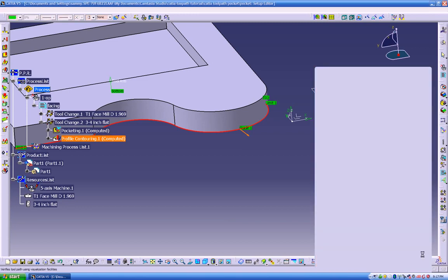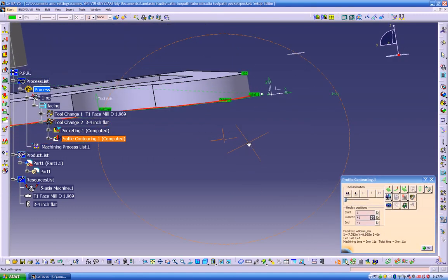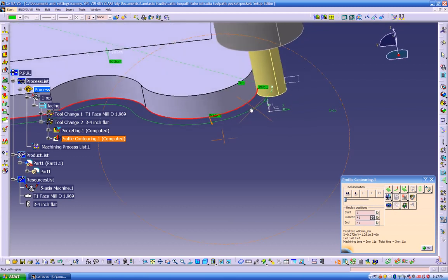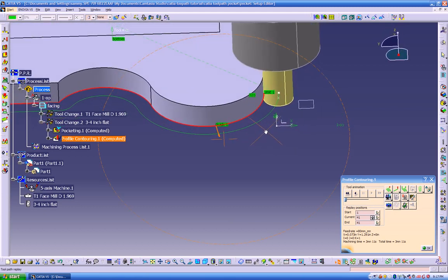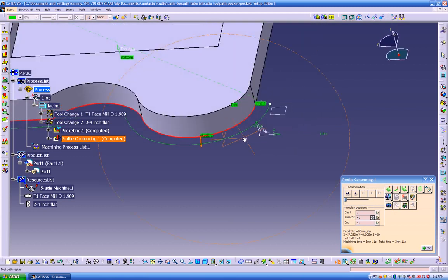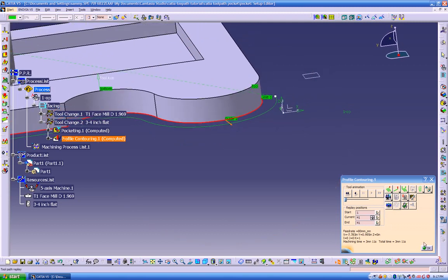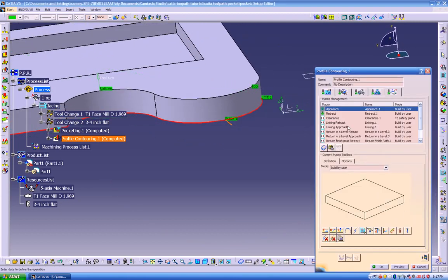let's do toolpath replay. So as you see, the tool starts right here at the bottom, right into the part, which is not recommended. It's gonna make a big mark into the part. So that's why I always have to lead in and lead out. Start outside, come back very nicely, and the part is gonna give a nice finish. So that's why I added the circular motion.